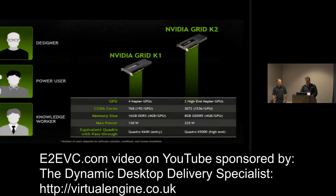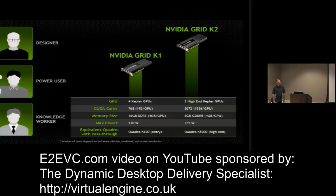A couple of speeds and feeds real quick here. As I said, single by 16, double width. These are passively cooled, so it requires servers that allow you to have the proper airflow and the proper SBIOS that's been cooked by the OEM vendor. So it doesn't fit into anything out there today. You have to go with a list of certified servers. But notice that we're drawing 130 watts here, so you're going to need a 6-pin connector coming off your power supply. On this one, we're pulling 225, so you need an 8-pin connector coming off of there.